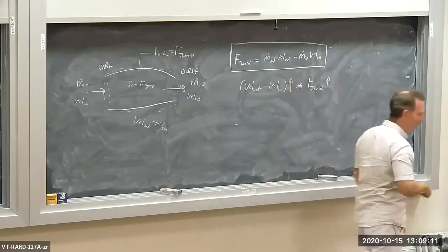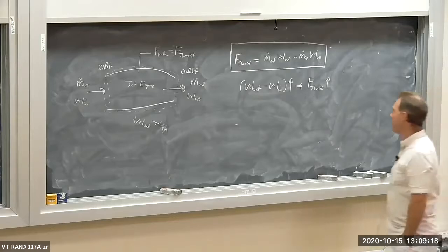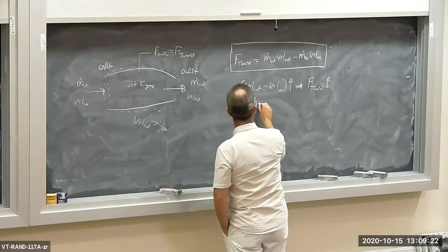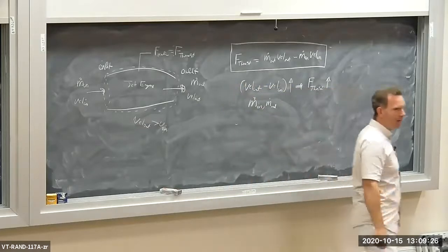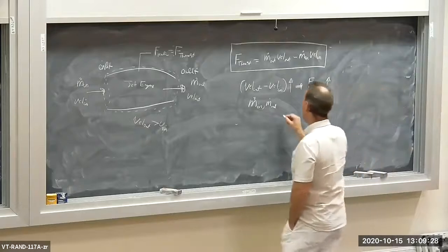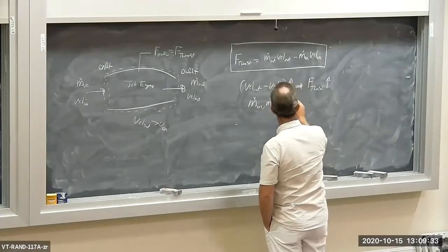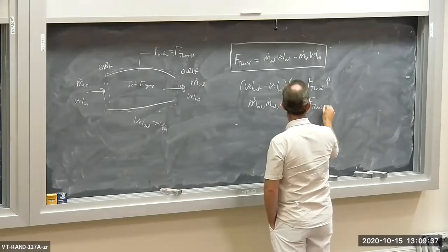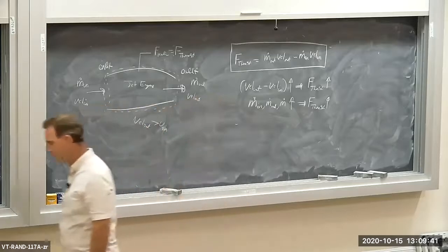As you increase the outlet compared to the inlet velocity, you accelerate the flow, you get an increase in thrust. It also says that as you increase the mass flow rate, m dot in and m dot out, as that goes up, thrust also goes up.